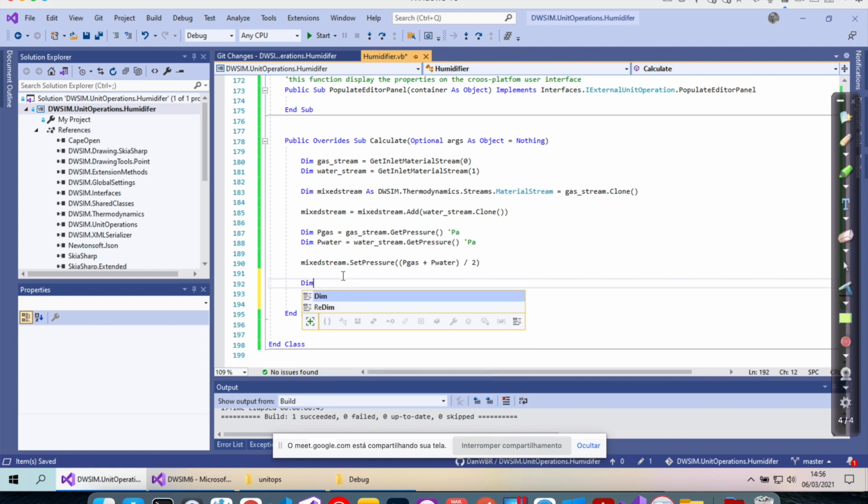Okay, I thought you would just add the component water. The add function will auto calculate the new mole fractions of each component. No, it just sums the flows and the compositions, and it does set the enthalpy and the temperature, but since we are not sure how it does, it is better for us to set them manually, just to make sure that we are doing it right.